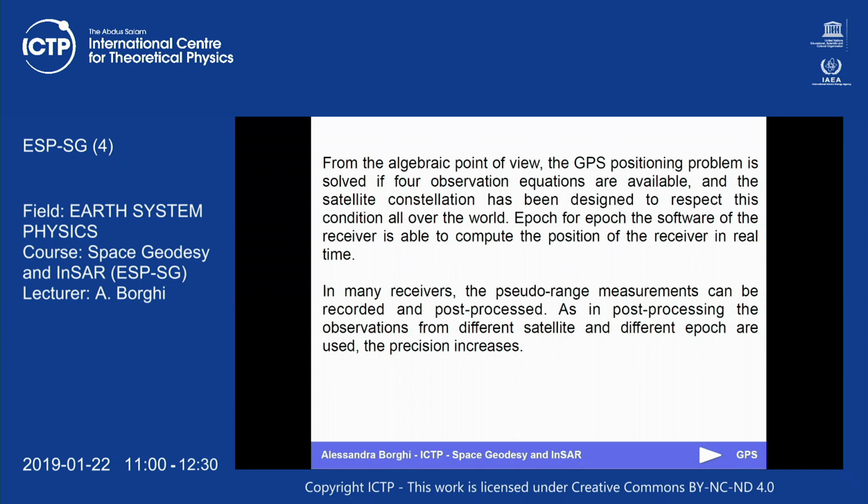But I have more observations, because what happens is that we don't receive in continuous; the signal is sent continuously, but we can record it at a given frequency in collecting data. In the past, for instance, for geodetic applications, we used 30 seconds. Every 30 seconds we recorded a data observation, or every 20 seconds, 10 seconds.